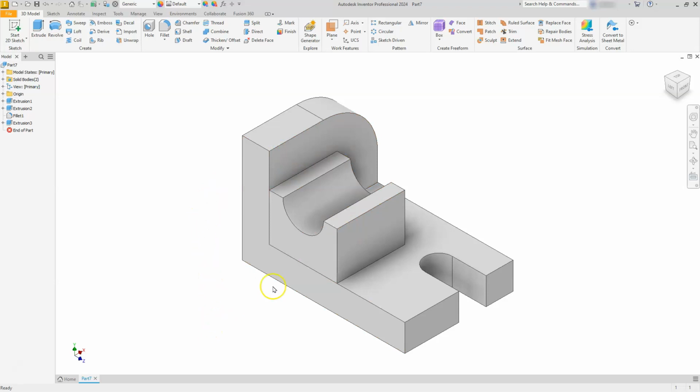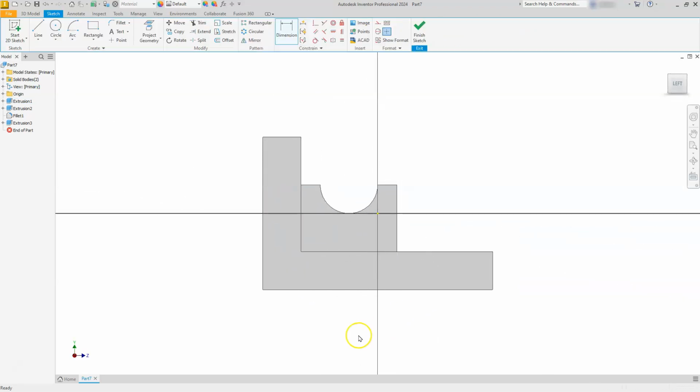I'm going to keep going, and I'm going to put the wedge that's located here. So I'm going to select this face. Once again, select the green plus icon here. That's going to start my new sketch. I'll start a line. Start at this green endpoint. Place at that endpoint. Come back to that green endpoint. And then back up to the original.